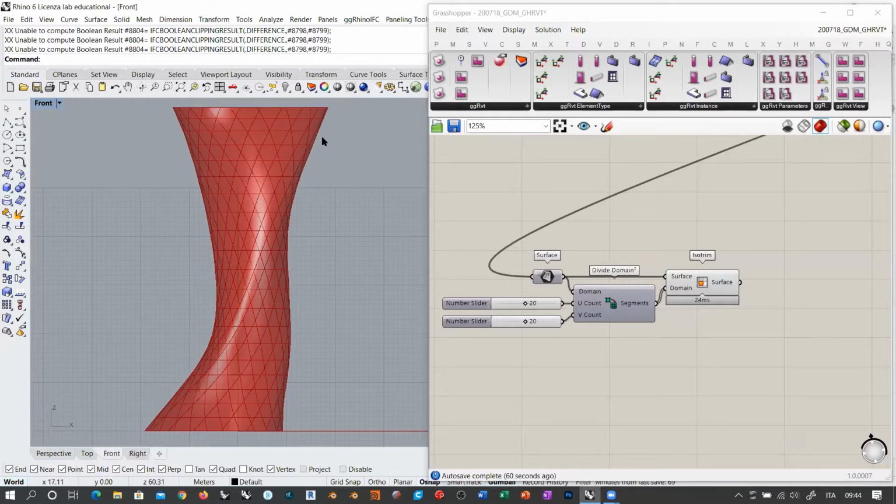And also you will notice that these horizontal cuts are not absolutely horizontal, so that there might be some horizontal distortion. So if you want to use these cuts here as panels for a facade system, you will have lots of problems, okay? So this is eventually not a good approach because you are obtaining some kind of weird geometry.